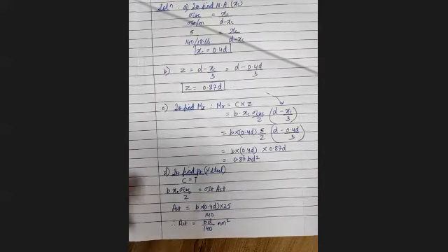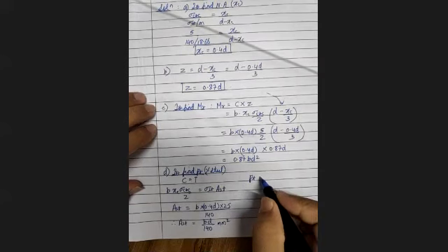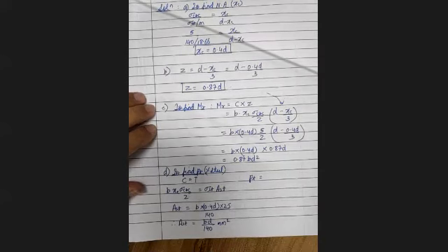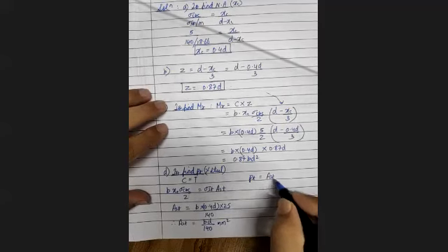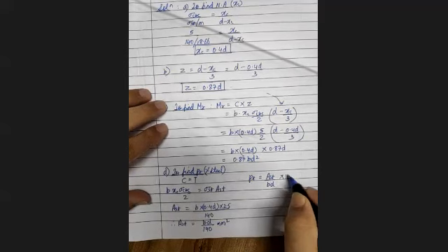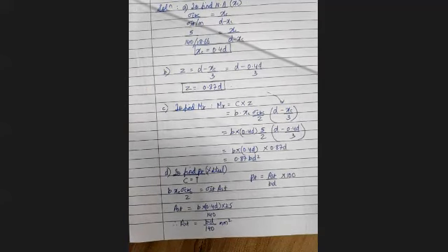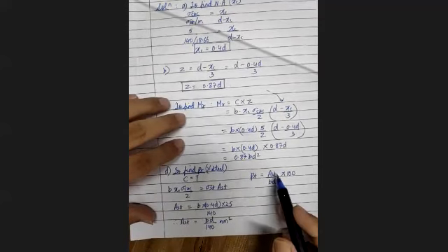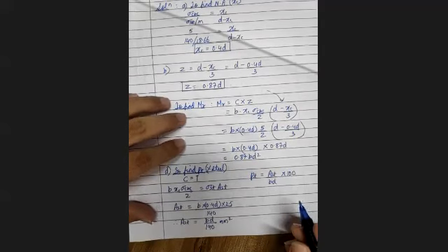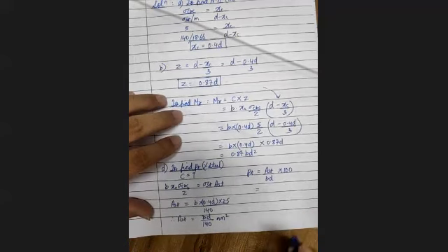Is this fine? So now we will find out percentage of steel, that is PT. Percentage of steel is given by AST upon BD into 100. Absolutely correct, Aditya. 1 upon 140 BD. So now we know that percentage of steel is given by the total amount of steel upon the cross section area into 100. Remember this, we are taking the effective depth in design.